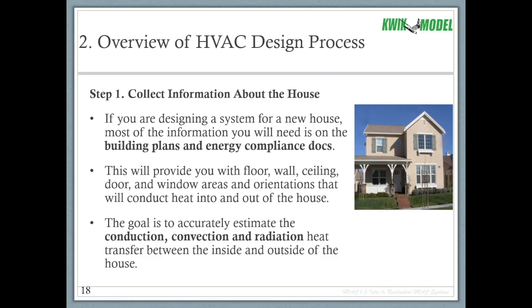So the information about a brand new house should be pretty readily available. This will also provide you with the floor, wall, ceiling, and door and window areas and orientations that you need, because you're going to have to plug those numbers into a software program that will calculate how much heat is conducting into the house in the summertime and out of the house in the wintertime. The goal of collecting information about the house is to have enough information so that you can accurately estimate the conduction, the convection, and the radiation heat transfer between the inside and the outside of the house.